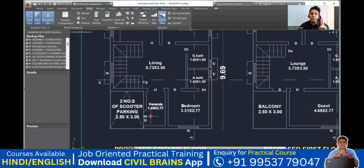You have a small veranda portion here, which is 1.40 by 2.77. Always remember, the first digit stands for the horizontal distance and the second is for the vertical distance. Okay, and then you come here. It's an opening. Opening in the sense you don't have any door here. Wherever they have written D, it means there is a door. MD stands for main door and O stands for opening. Opening in the sense you don't have any door, it remains open. That is why it is written O.